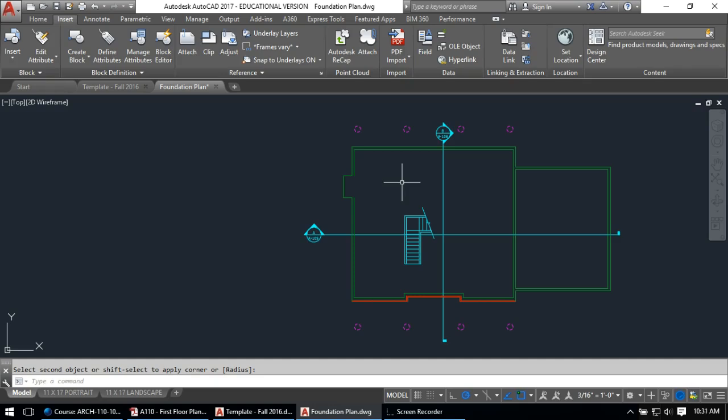The reason is walls, if it's a bathroom or even a kitchen or really anywhere, could have a different kind of finish which changes their wall thickness. So if you're dimensioning to the edge of the wall and you go and specify a certain kind of thickness, it could change the real wall thickness, and that could offset a room on the other side inappropriately.